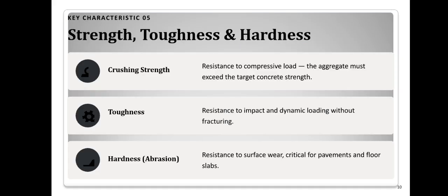Another important property is strength, toughness, and hardness. Strong aggregates help concrete resist compressive loads. Tough aggregates withstand impact, while hard aggregates resist abrasion, making them suitable for pavements and industrial floors.